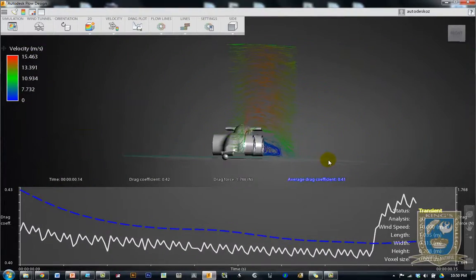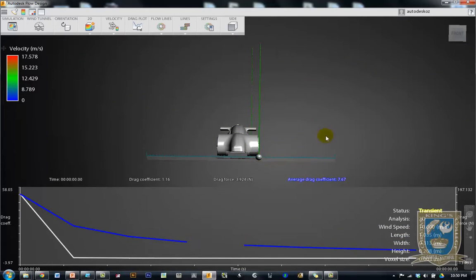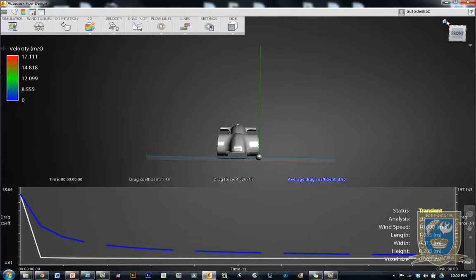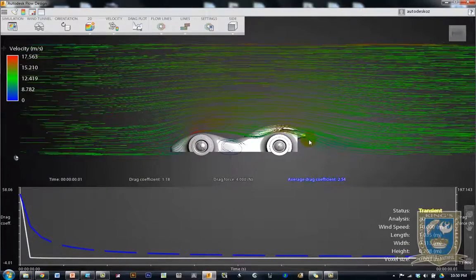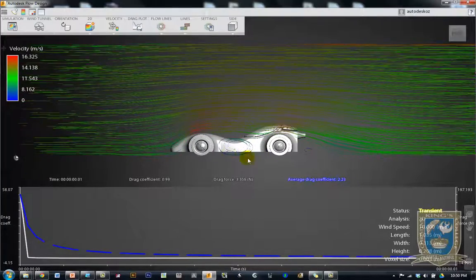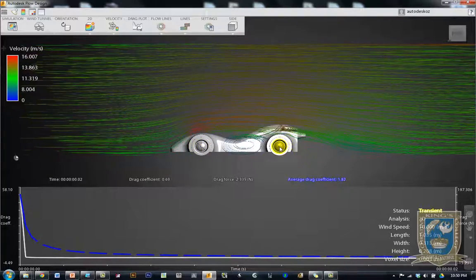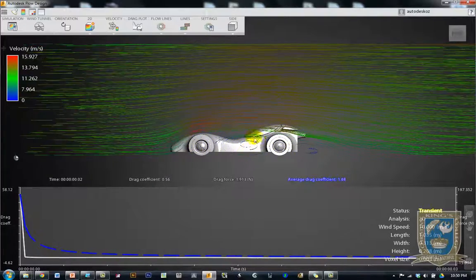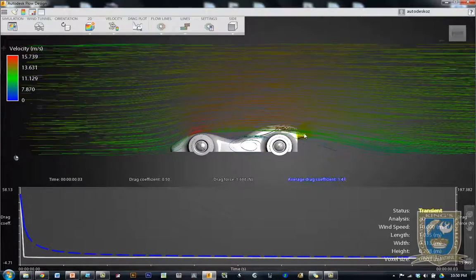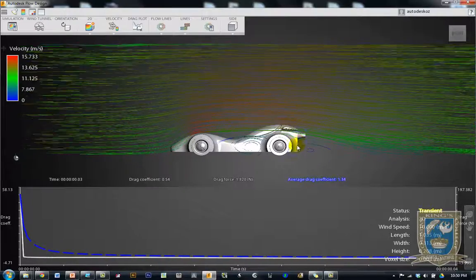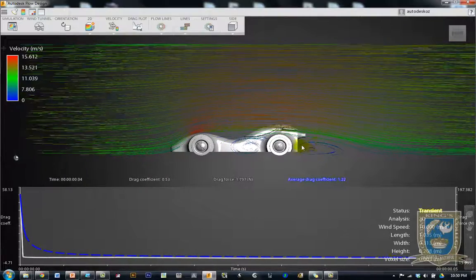Opposite mouse click, move it around, drag it out as far as you can. It'll go right out to the edge of the wheels. Go back to the little house, zoom in, and again, we're right out on the edge of the guards now, so right where the edge of the wheels are. Very similar, but if you notice the turbulence is here, but nowhere near as much turbulence. There was a big pocket of turbulence behind the vehicle before, behind this flat edge here. So you've now got a bit of wind escaping, a little bit escaping, and you've only got a smaller pocket.